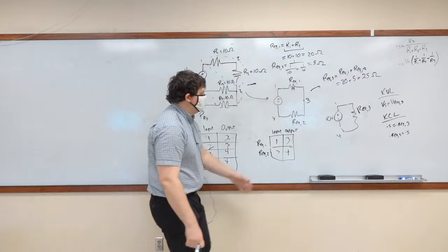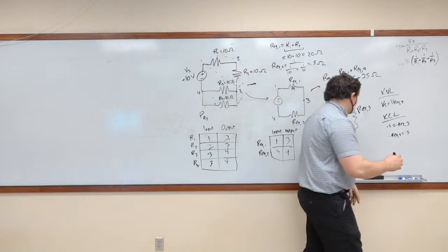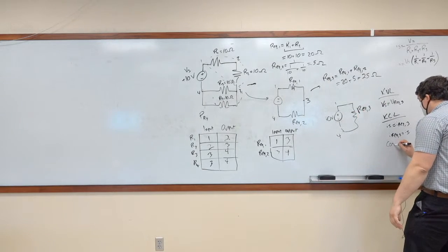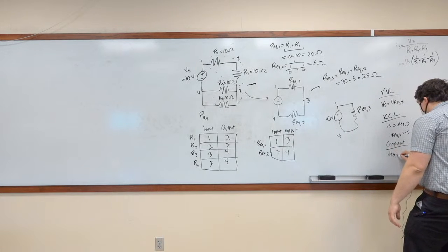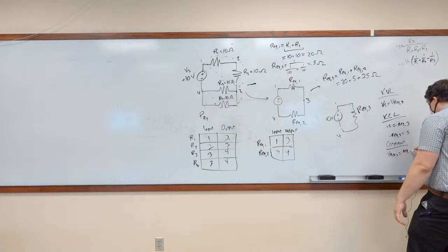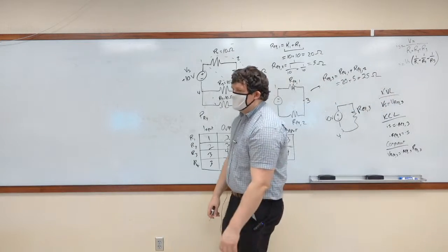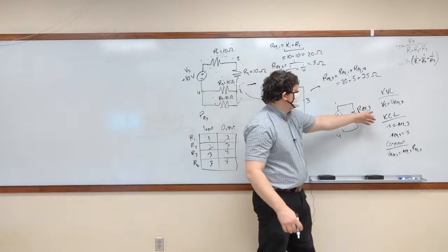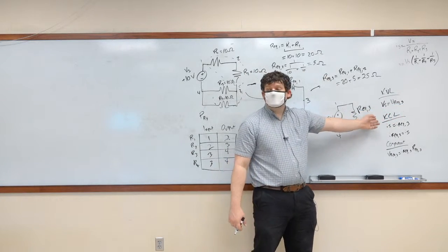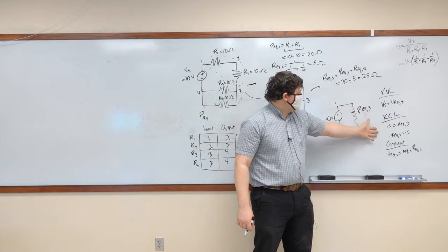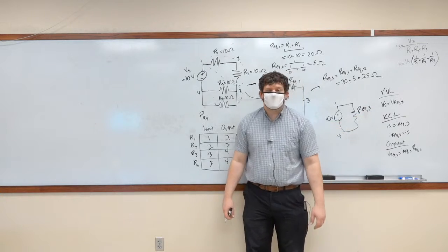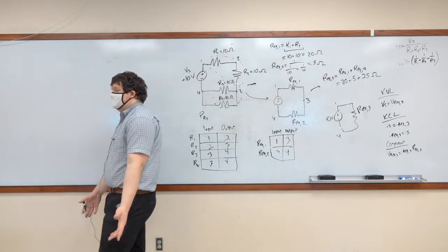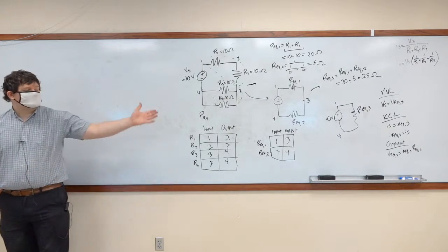We also have our component equation, and that is VREQ3 is equal to IREQ3 times REQ3. Well, we know that VS is equal to VREQ3. We know this is 10. We know that the currents are equal. So if we solve for the current that's going through IREQ3, we can find the current coming out of the battery. We didn't need to solve all of those other components.